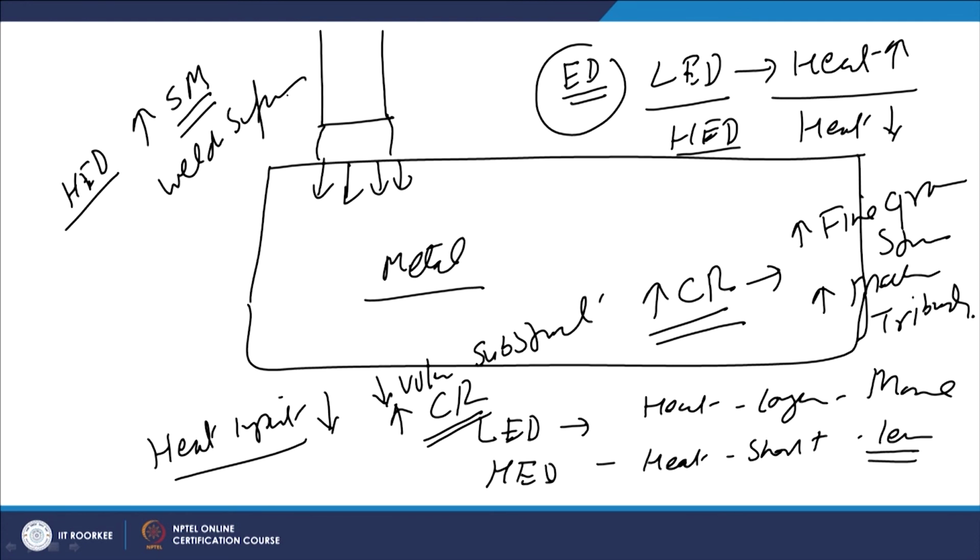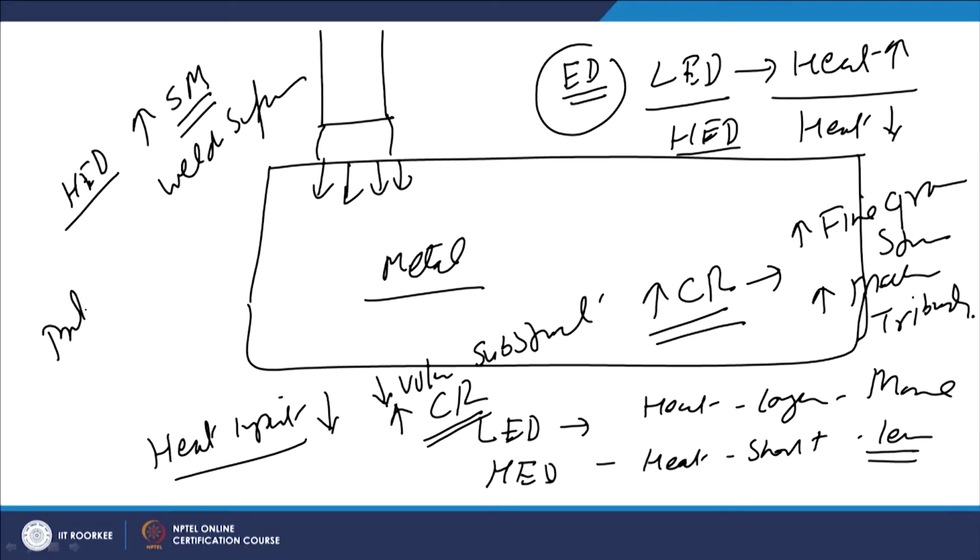So, if we have the laser, electron beam, plasma arc, gas welding, all are of different energy densities, and that is why they offer different kinds of qualities. So, each process differs in terms of the protection and in terms of the energy density, and that is why they offer different qualities of the modified surface layers through the weld surfacing. About other aspects related to thermal spraying, I will be talking in the subsequent presentations.